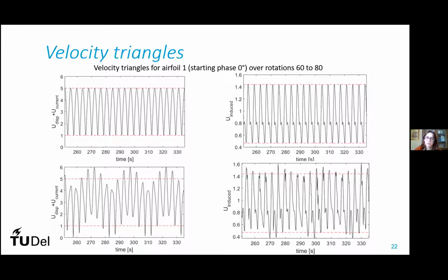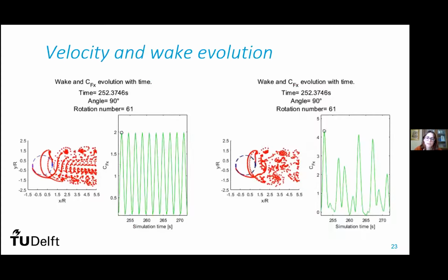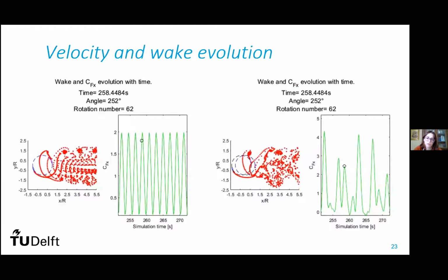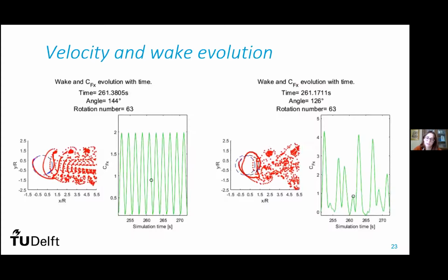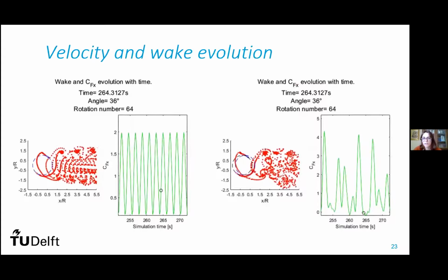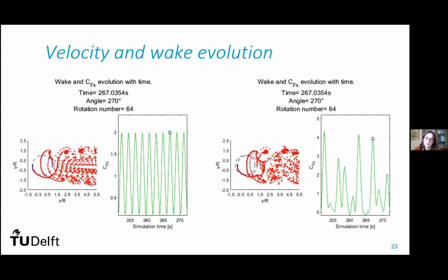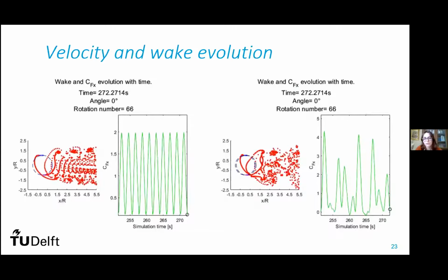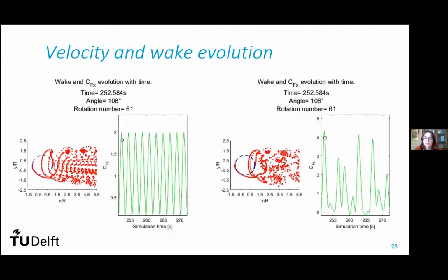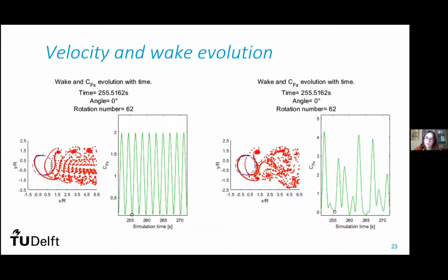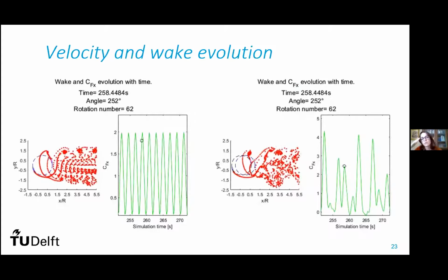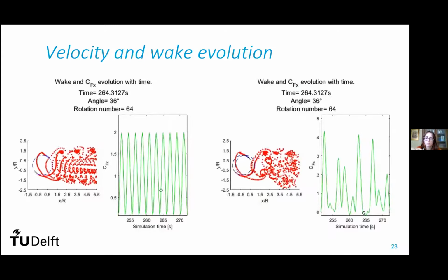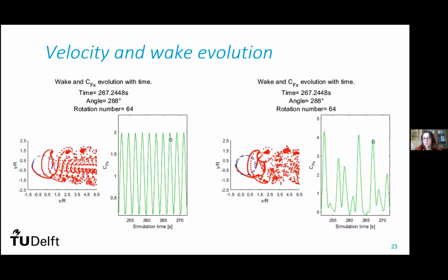And it is very interesting to look at the induced velocity, because this is, for example, the evolution of the wake, and you can see that the evolution of the wake for the only current case on the left, and instead for the surge case on the right, is very different. When you have the displacement of the rotor going downwind, you increase the blade vortex interaction in frequency, which leads to a less smooth graph. When instead you go towards the left, so more upwind, the rotor stops interacting with the wake, so the graph becomes more smooth.